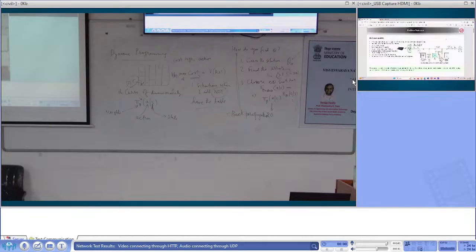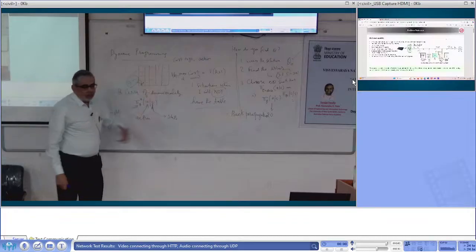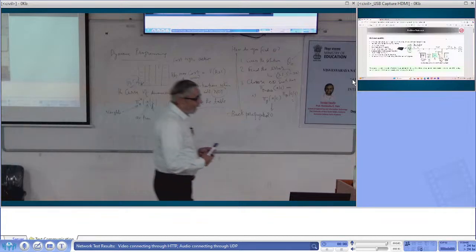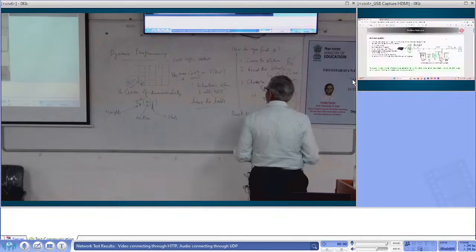You don't know the system, but you know under which conditions you need to award rewards, and one of them, if you are doing battery scheduling, is reducing the overall cost you pay to the utility company. So you know how to reward the algorithm. Okay, using those rewards, it will convert the random information to something very powerful, very specific in the form of a neural network, which you can use to do these tasks repeatedly. Okay, so this is what I want you to take from our discussions. Any questions?